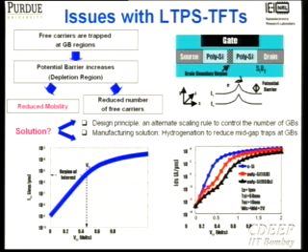The interesting thing to note is the fact that this is not a bulk technology. What does it really look like? It looks more like an SOI technology, very thin body SOI. If I can make my body really thin, then of course it looks like a good transistor. Of course, there can be grain boundaries.